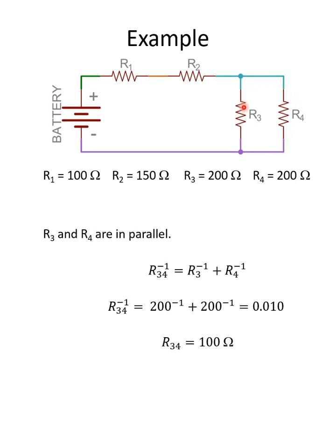The first thing we should do is see if we can turn this parallel bit into an equivalent resistance. So let's see what the resistance of 3 and 4 together is. I'm going to call it R34, because using some imagination, I'm going to figure out what their effective resistance is, imagining pulling those resistors out of the circuit and replacing them with a single resistor.